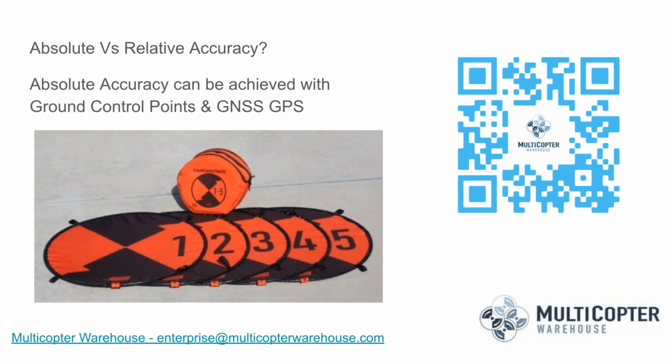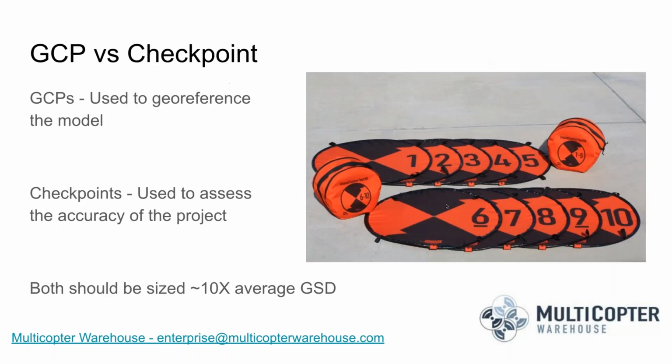And then you can enter that data within Pix4D, marking those points that are very easily identified by having the numbered ground control point there. That'll allow you to get your data geo-referenced to what we'll call global accuracy. And that's really how you get the best quality results if you're trying to use this data for additional mapping or adding in with other GIS data.